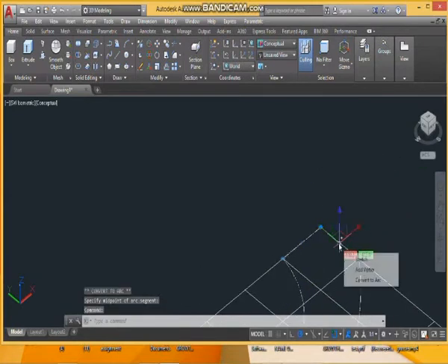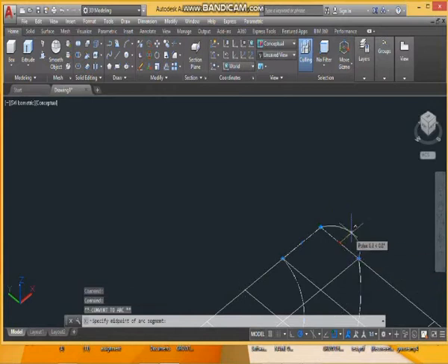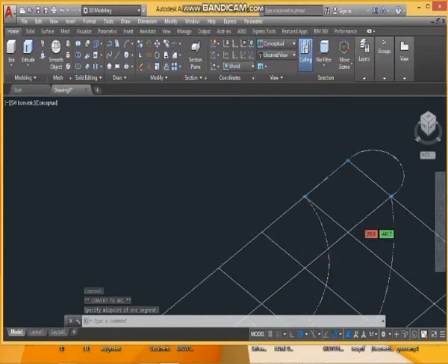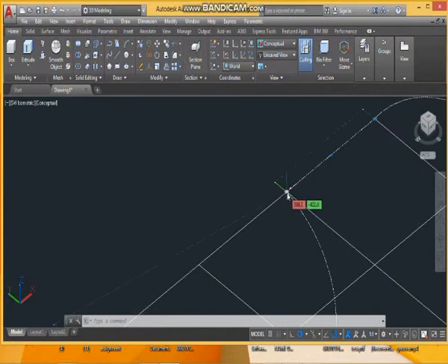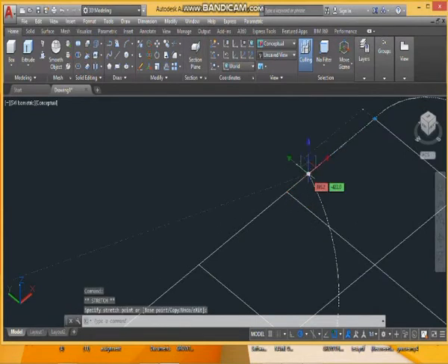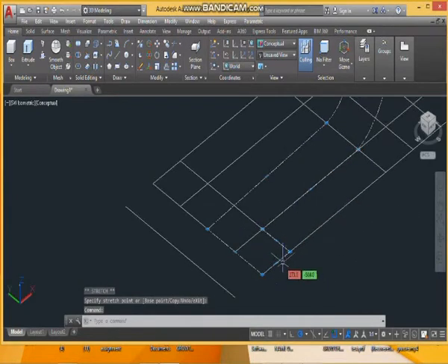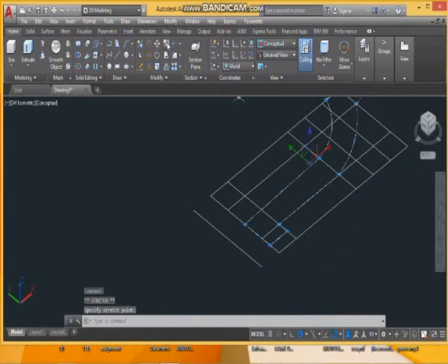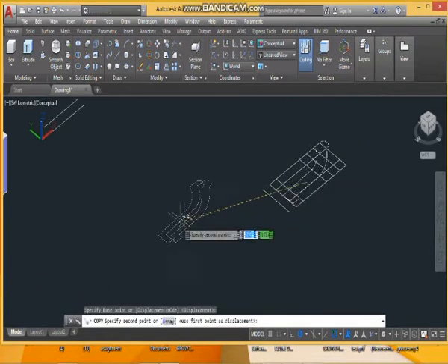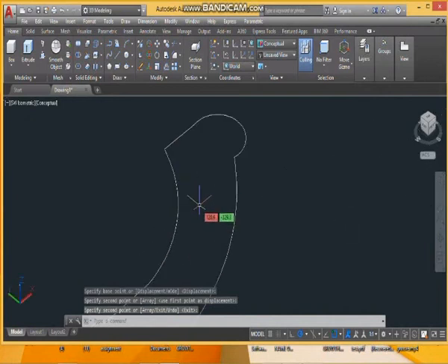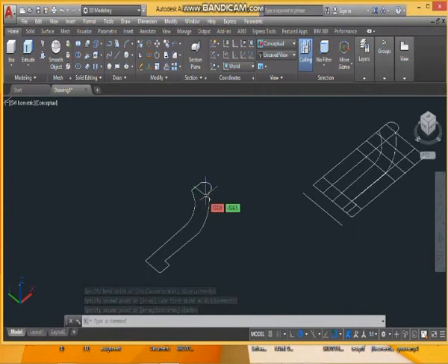When you take the cursor to the center, it gives you 3 options. You choose where you can convert the line into an arc. We just try to adjust it to have a good shape. When you pick a summit and shift it, it goes easily, and that is the advantage of the polyline. Now let's take it away from the grid and see if we can carry out some other adjustments. I see the need for us to adjust it.